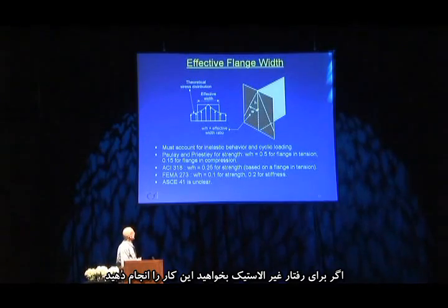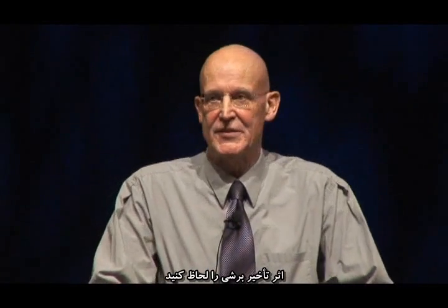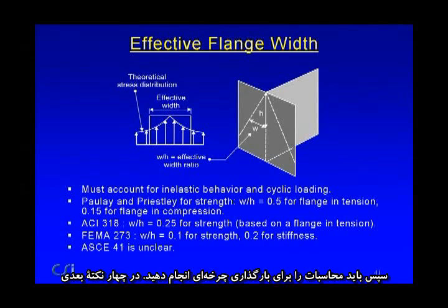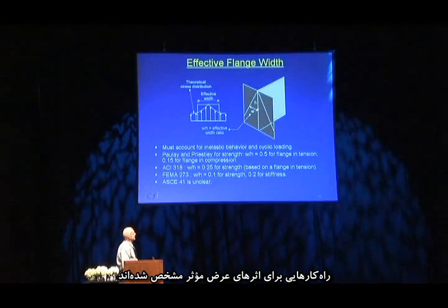But when you do this, if it's inelastic, it becomes a little more complicated to figure out what is the effect of shear lag. Firstly, you must account for inelastic behavior, and you must account for cyclic loading. And in the next 4 points, I've indicated what suggestions have been made for the effective width.